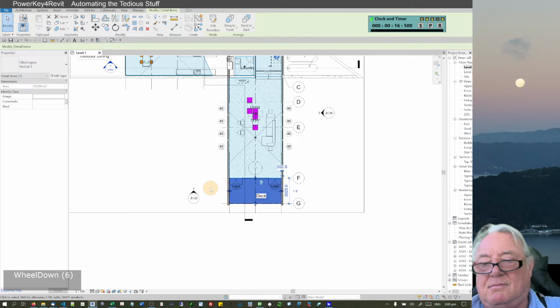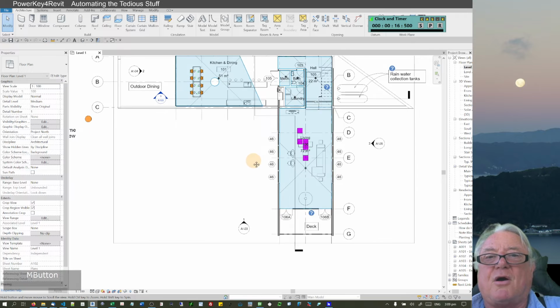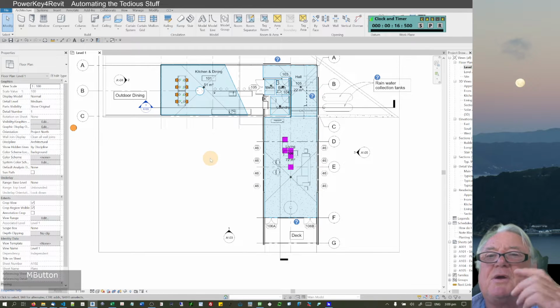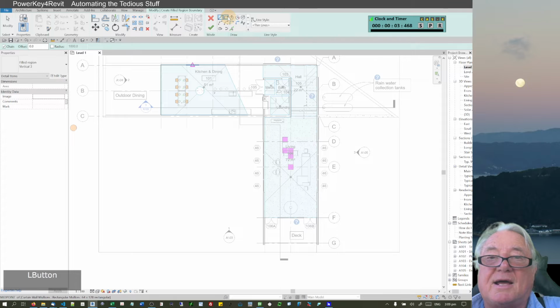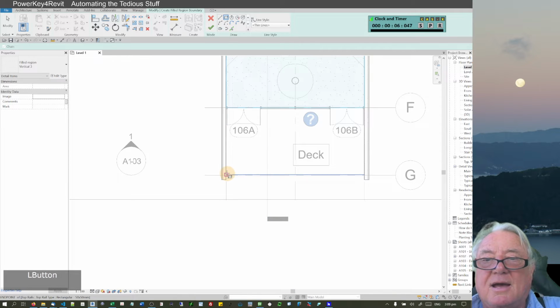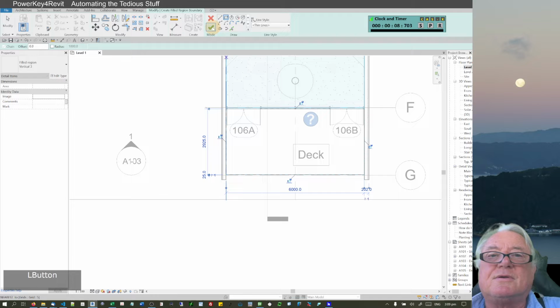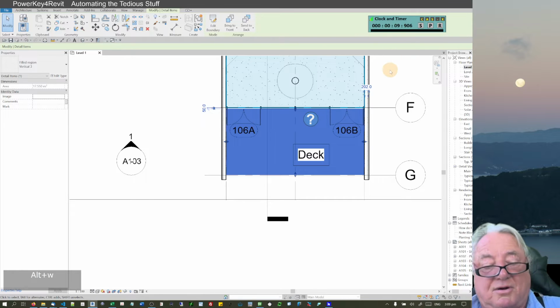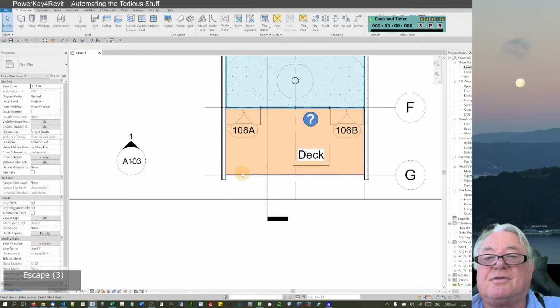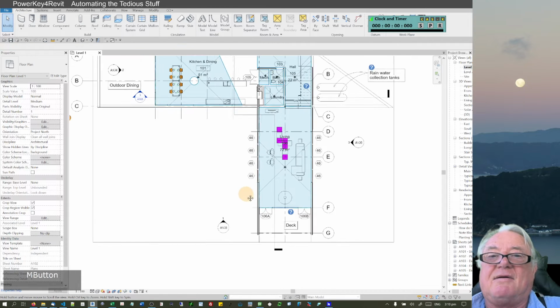We'll zoom back in and delete, so that we've got the whole item on the screen. The next one we're going to do is exactly the same thing using the region command. We're going to clear that, start, and go Alt S, click on that R4, which brings us into that. We're now going to select region, come down here, select 1 point, 2 points, go OK and Alt W. So that's taken us about 9.96 seconds, so we'll say 10 as a rounding point. So we go R through there. Now we're going to zoom back out again.